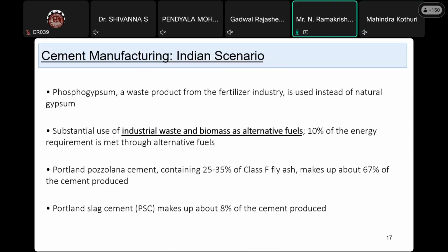PPC cement has fly ash content of 15 to 35%, and 25 to 35% is given by the code. Nowadays most people are using Portland pozzolana cement. Slag cement is also now picking up. About 8% of the cement is being produced as slag cement, and the substitution can be taken up to 70 to 80% in the case of slag, whereas up to 30 to 35% only in the case of fly ash, as per the code.